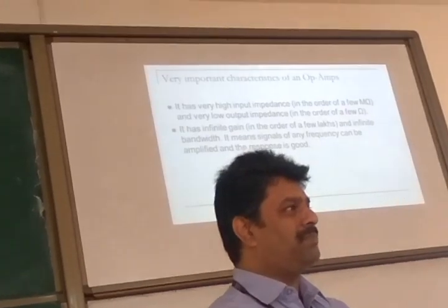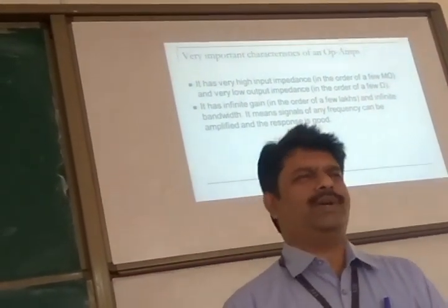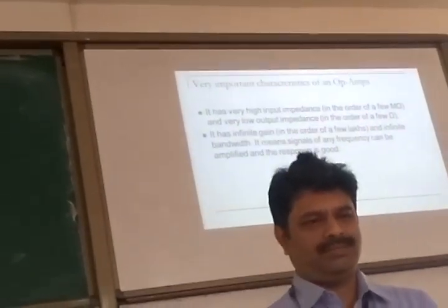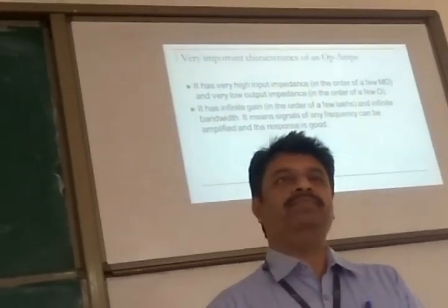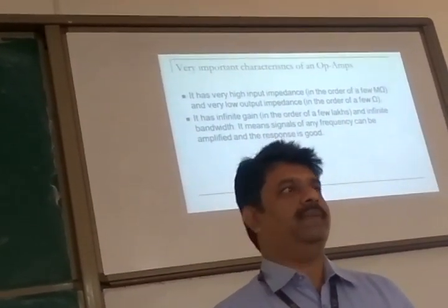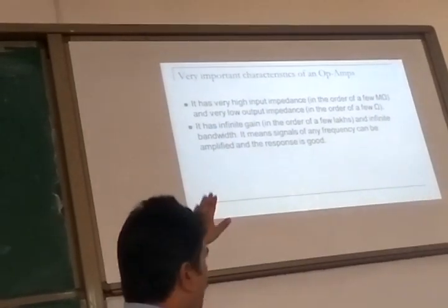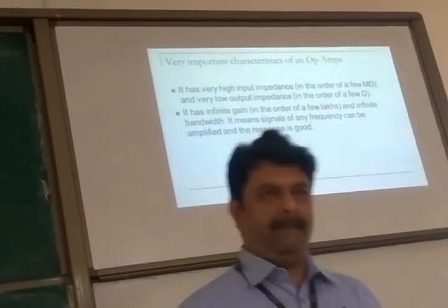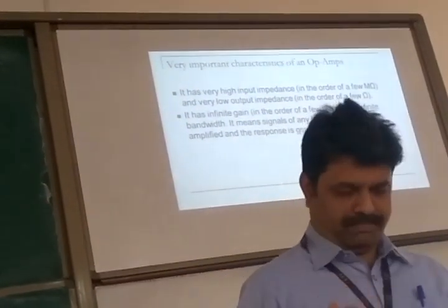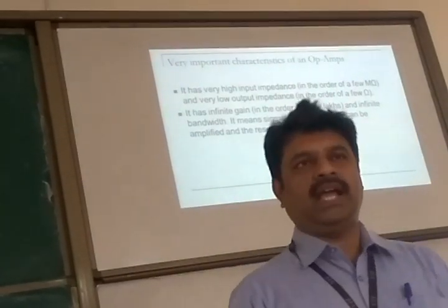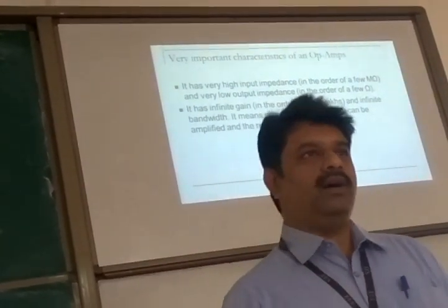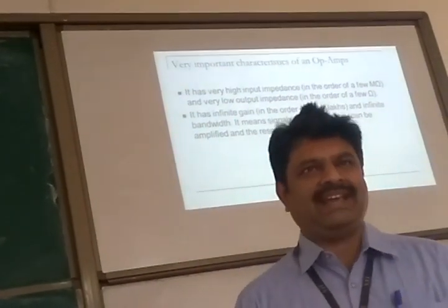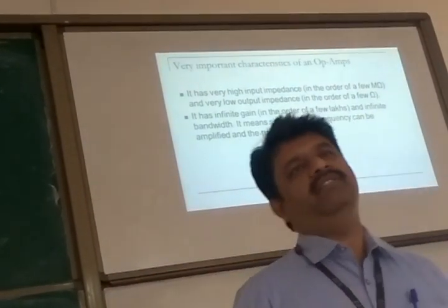I very carefully use the term almost because it is true to a greater extent. It will treat them equally, but there will be minor partiality. But for all practical purposes, we say it treats all the frequencies equally. Okay, that's a good look at it. All four are very important, and the op-amp has all four. It is a man-made device. It is purposefully designed like this. We want high bandwidth, we want high gain, we want a high input impedance, we want low output impedance. These are all ideal characteristics of an amplifier. They have designed it with all this.